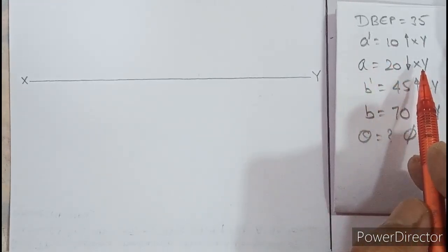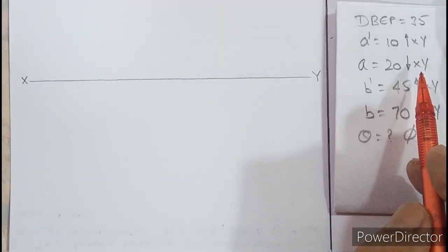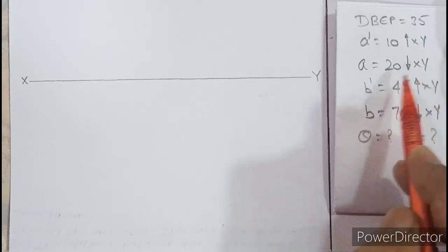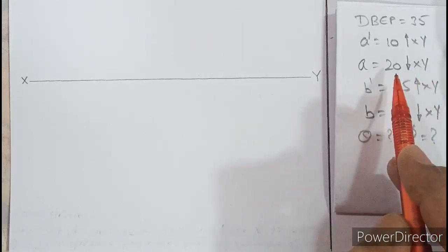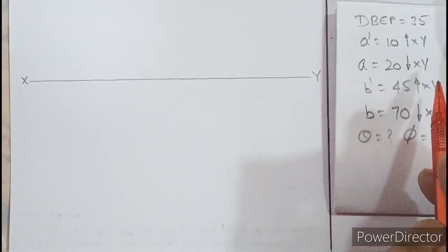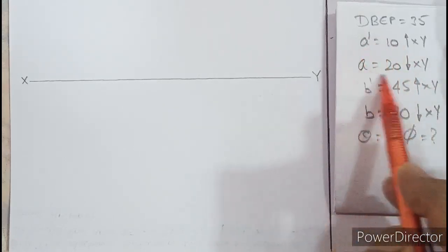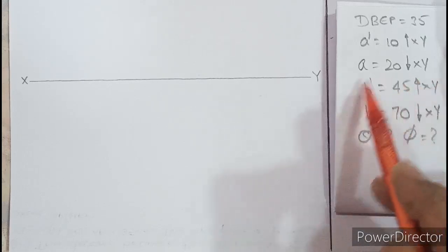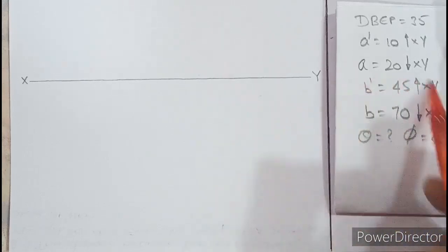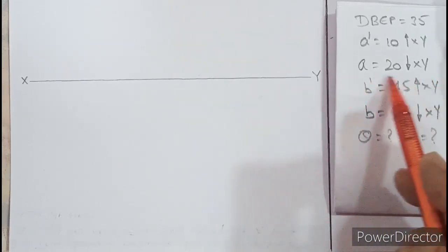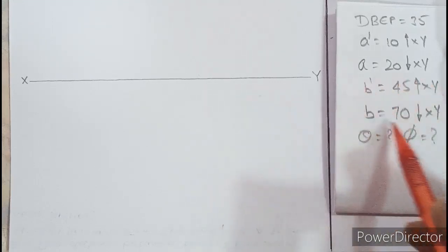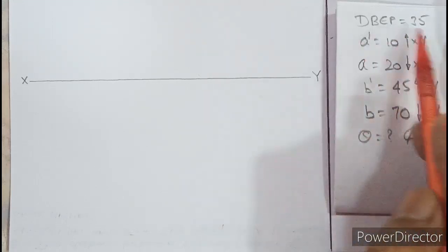First decide which point will be fixed and which point will be rotating, because out of the two endpoints of a line, one should be fixed and the other should be in a rotating mode. Let us always take the starting point A as the fixed point and the moving point be B. The concept should be thorough that a locus is available only for the moving point. The fixed point will never have a locus.